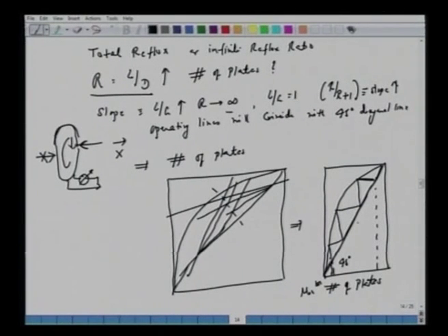And since the operating line is now y equal to x, one can obtain analytical solutions for the minimum number of plates if we have certain assumptions, like the relative volatility of A over B is constant. So one can do some calculation here.